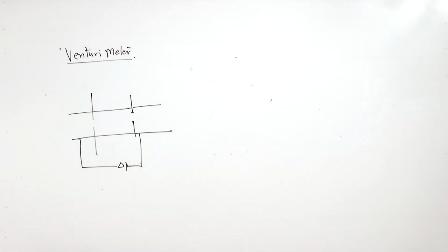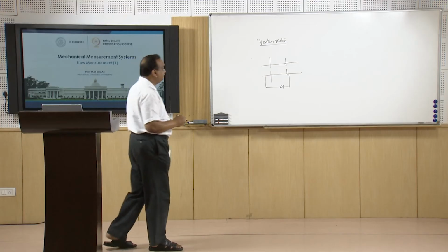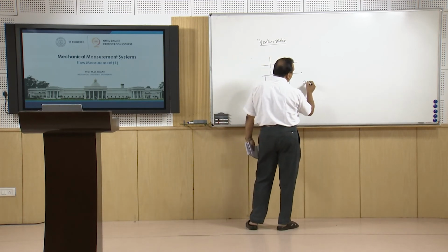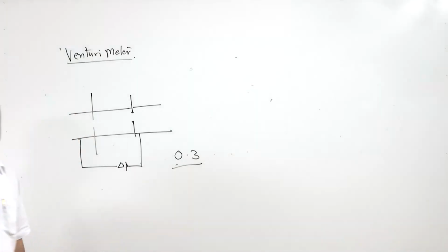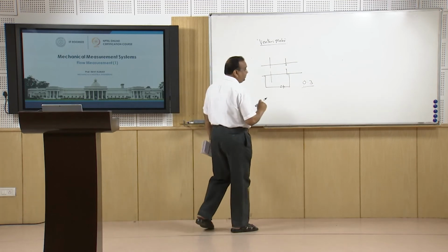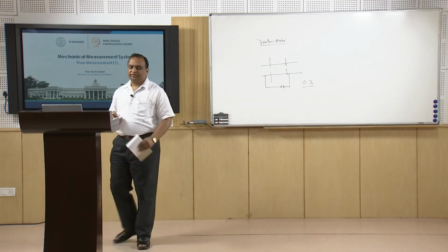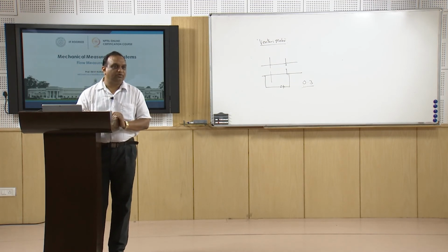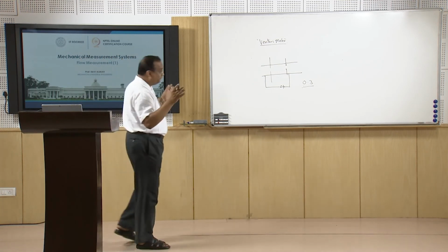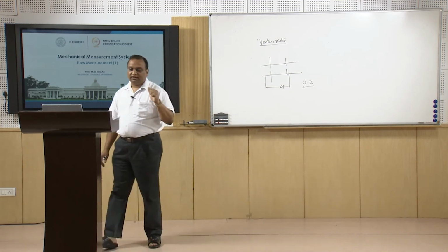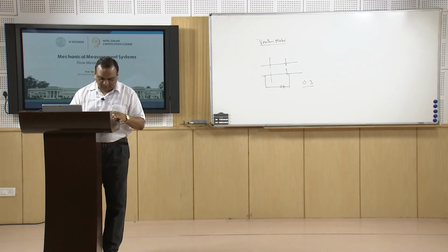So, for large diameter tube flow, the orifice meter is good, but it is an obstruction type of device and pressure recovery is poor, pressure loss is high, and the coefficient of discharge may be as low as 0.3. So, it also depends upon the design. Normally for small diameter instruments which are obstruction type, they are made of brass, right, because brass has a smooth surface, so losses due to friction are less. But if we have to go for a large diameter, then we have to go for another material for the fabrication of this type of instrument.